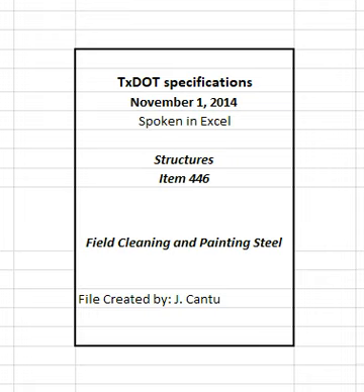4.7.3.2.2 Tool cleaning. Meet the requirements of SSPC SP2 or SP3 unless otherwise shown on the plans. Probe the perimeter of peeled areas of paint with a putty knife to ensure remaining paint is tightly adhered. 4.7.3.2.3 Water blasting. Meet the requirements of SSPC SPWJ4. Tight mill scale and tightly adhered rust and paint are permitted. Probe the perimeter of peeled areas of paint with a putty knife to ensure remaining paint is tightly adhered.